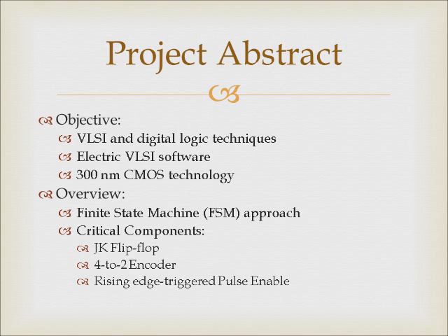A finite state machine is a model used to design both computer programs and sequential logic circuits by using states, usually in the form of bits, to keep track of past inputs. This vending machine utilizes a state machine to keep track of the money that has been deposited by the user. These states, in addition to the encoded input, are then used to determine the next state and possible outputs and/or